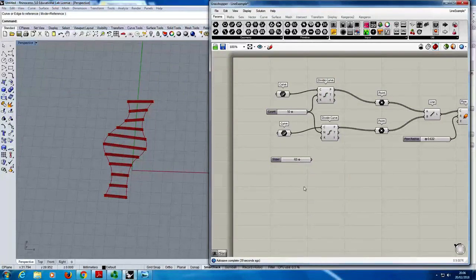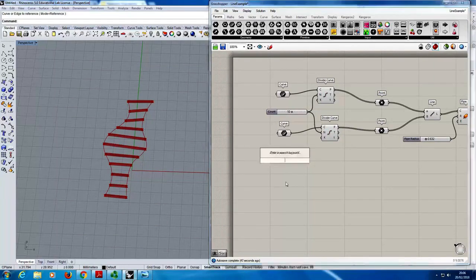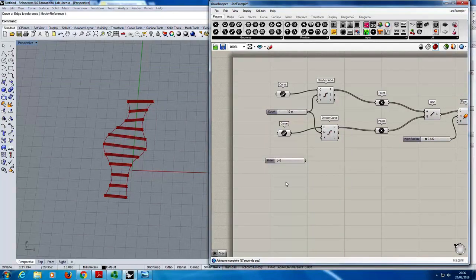So you can use that as a shortcut just to very quickly set up number sliders without having to keep going up here and into those options and setting it all up. What we can also do, if I type in here a number followed by 2 dots and then another number, so in this case 0..20, that will set up a number slider between those two numbers.